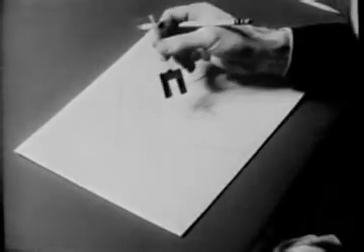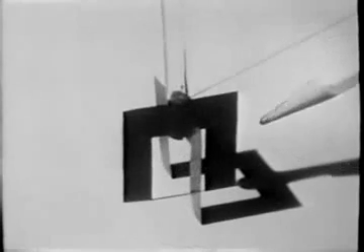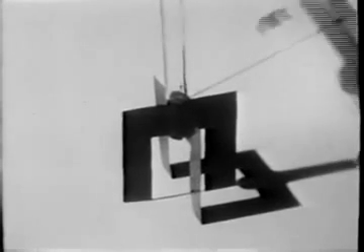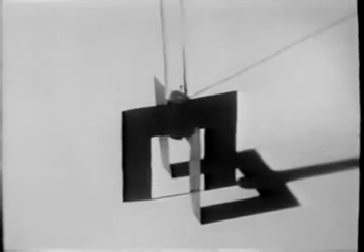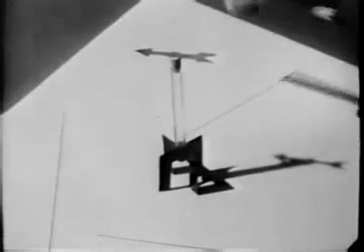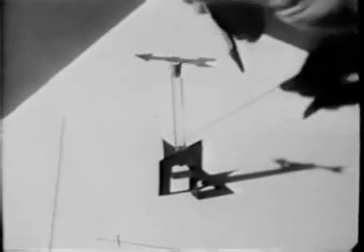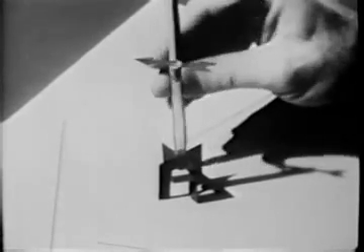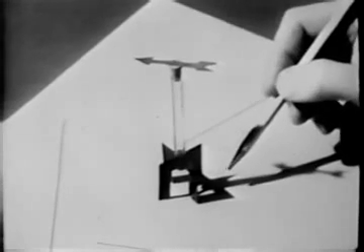It is exactly twice the angular velocity. This gadget is a vorticity meter, which floats in water with its axis vertical. The 2 vanes at the bottom are driven by the angular velocities of 2 mutually perpendicular fluid lines, so the arrow at the top turns at a rate equal to the average of these 2. That is, with half the vertical component of vorticity of the lump of water in which the vanes are immersed.